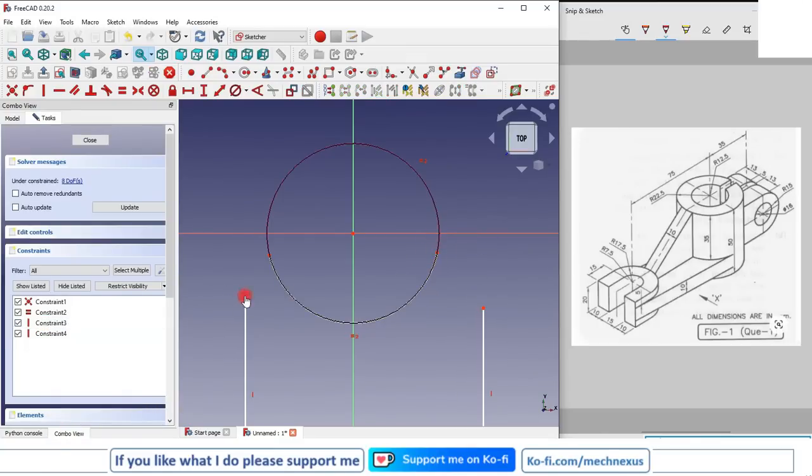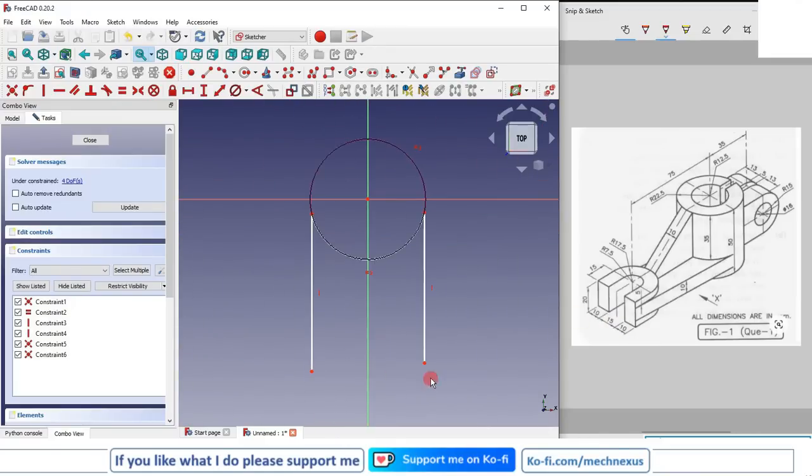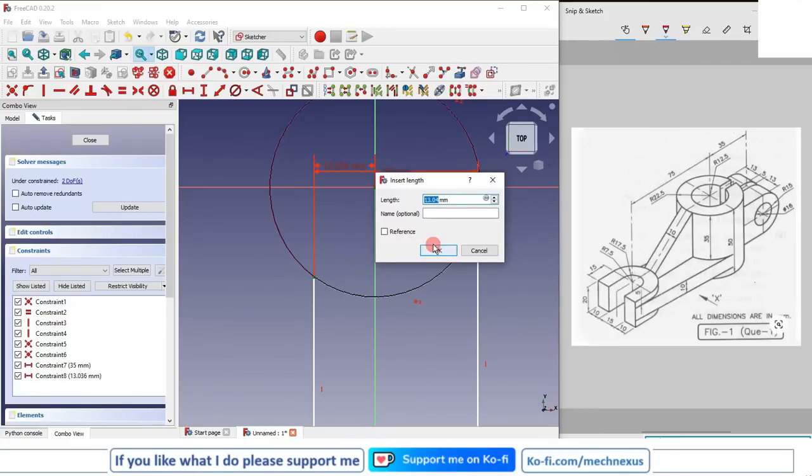Okay, now I will select this point and coincident, select this point and make it coincidence. So this is total 35. So I will give the dimension. I will select horizontal dimension. I will select this point and this point, and I will give the 35, and this point and this point, 35 divided by 2.